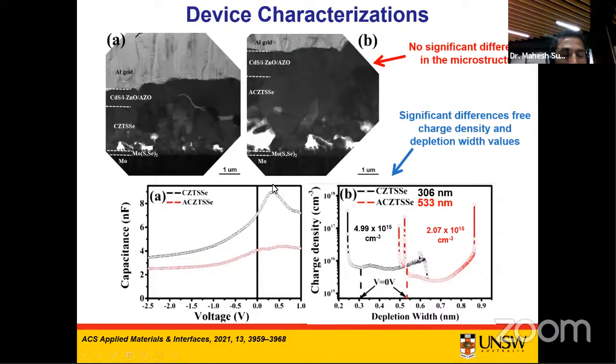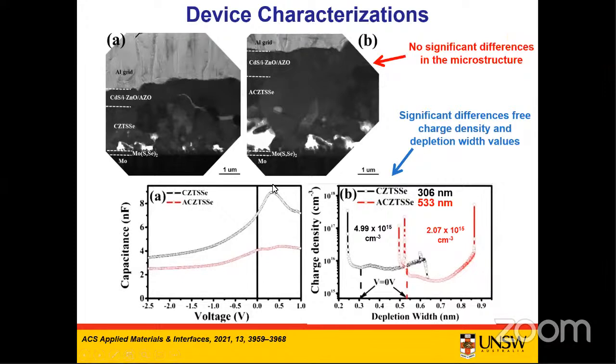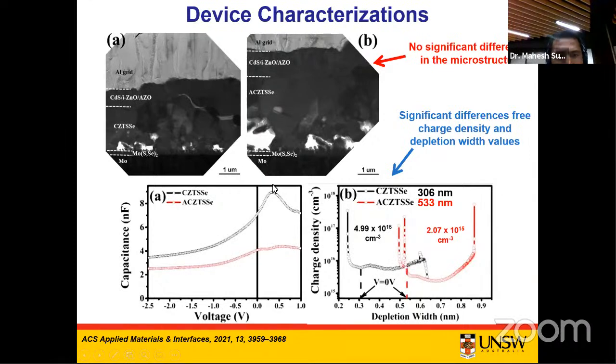So what we believe is that, benefiting from the silver alloyed CZTSSe, or partial silver substitution in the CZTSSe devices, and the further optimization of device parameters such as annealing pressure, sulfurization time, or the thickness optimization of the N-type CdS buffer layer, and many other parameters, efficiencies over 12% can be easily achieved with a low VOC deficit characteristic of about 528 millivolt in the case of the CZTSSe thin film solar cell. So this is all about the CZTSSe thin film solar cell.